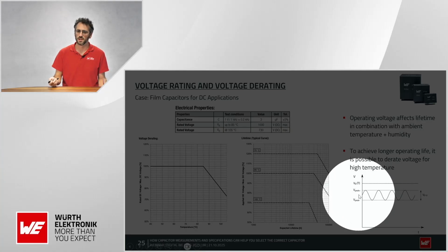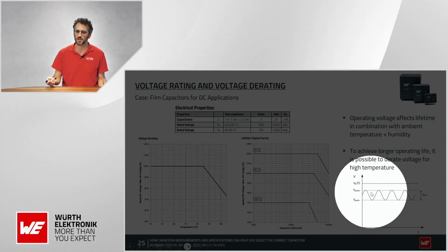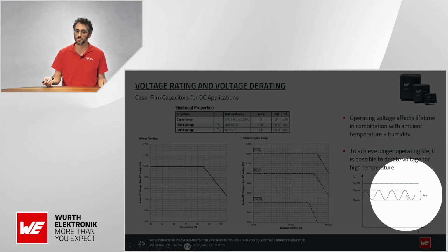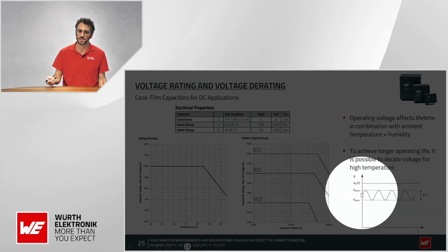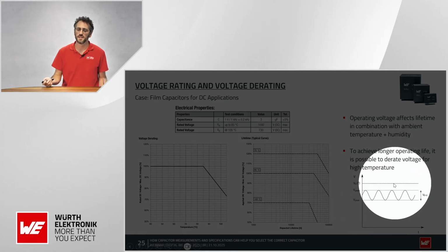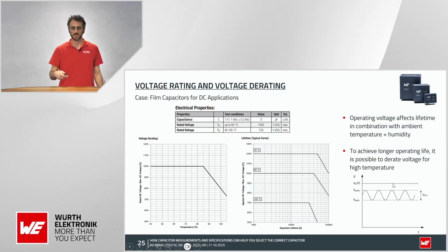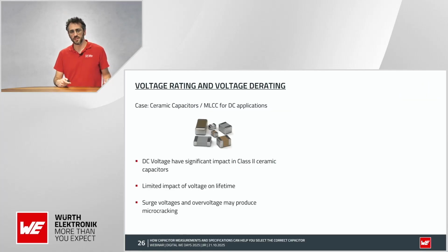So it is not allowed that you have average at rated voltage. This could mean that the peak voltage is much higher than the rated voltage, and you will probably not have the same lifetime.